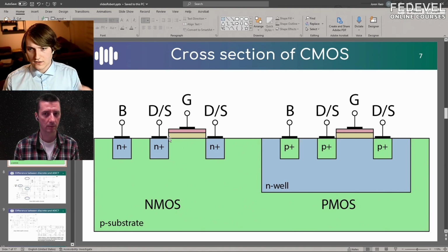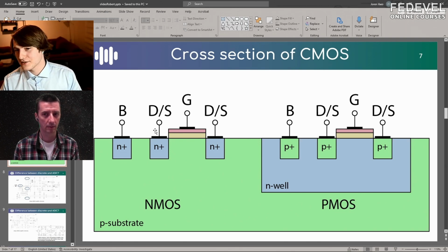With FinFET, it's kind of a mess because when you have a fin, where do you define it? You can define the width of a fin, but it doesn't actually correspond to any electrical specification of the transistor because the gate works in a fundamentally different way. And so they kind of gave up and they just make it smaller with every generation and give it a smaller number, but it doesn't necessarily mean anything on the technology anymore.